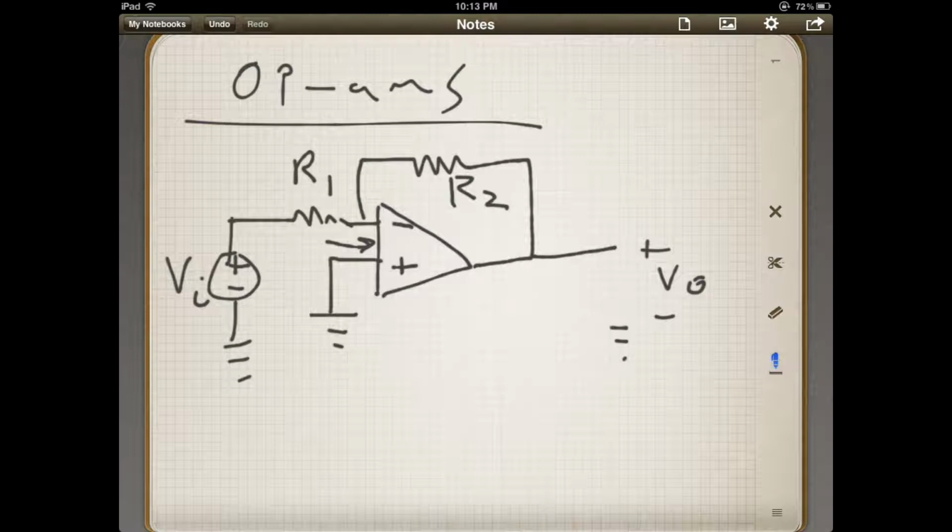What that will mean is that a lot of times you can hang an output on, let's say, a resistor stack and not rob a significant amount of current where it will skew your numbers. I'll show you what I'm talking about later. So that's a very useful tip: they have high input impedance.